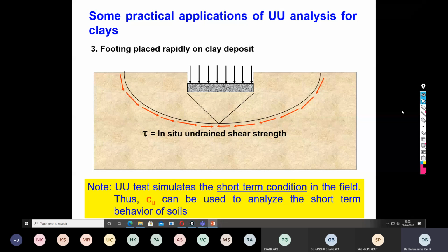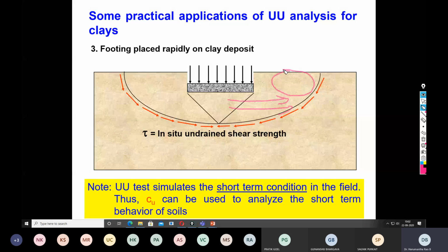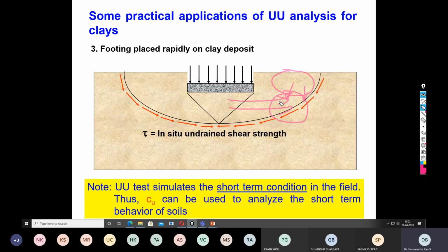When it is exerting the excess pore water pressure in the lateral direction, suppose the overburden soil is not able to resist it, then failure is imminent. So this is the reason the UU becomes the worst, while the CD condition is the safest.